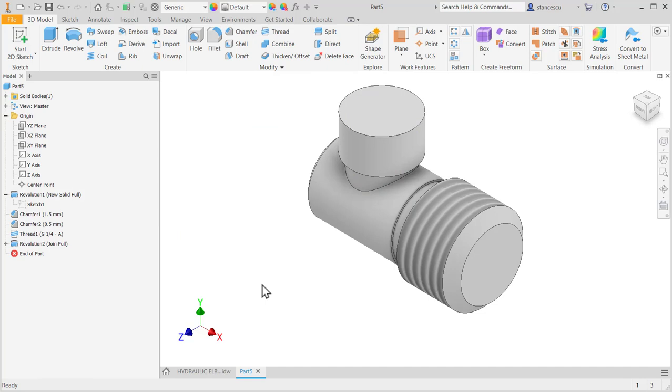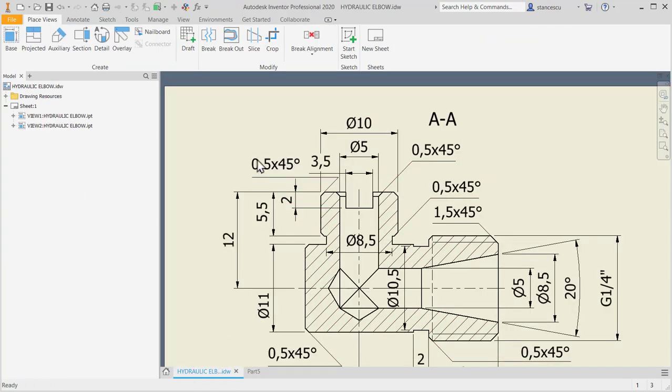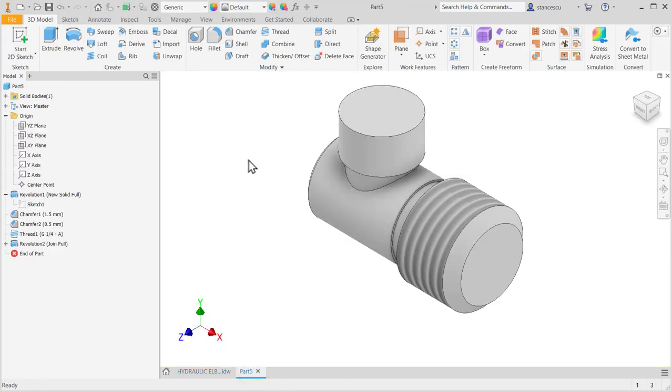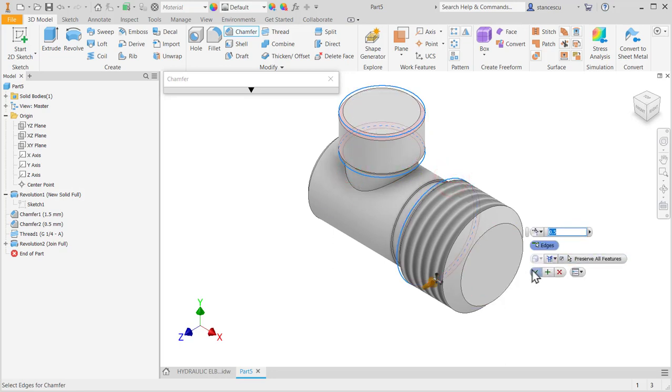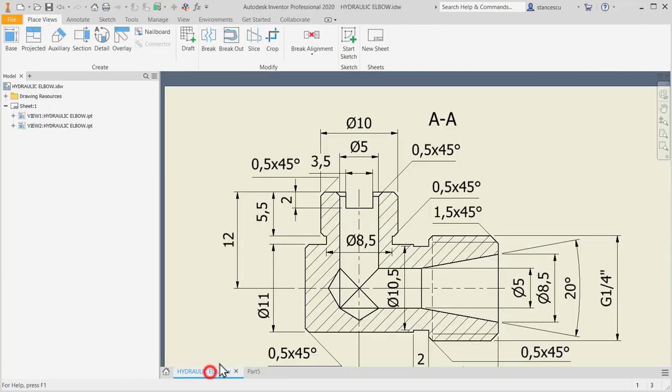Okay. It has a chamfer, two chamfers. There is another chamfer here, we forgot it. Yes, 0.5. 0.5 here. All are 0.5. This one, and this one. Let's apply them. Chamfer 0.5 is already selected, also here, also here. Okay, there is a channel here, but I prefer to start with the hollow cylindrical or revolving shapes.